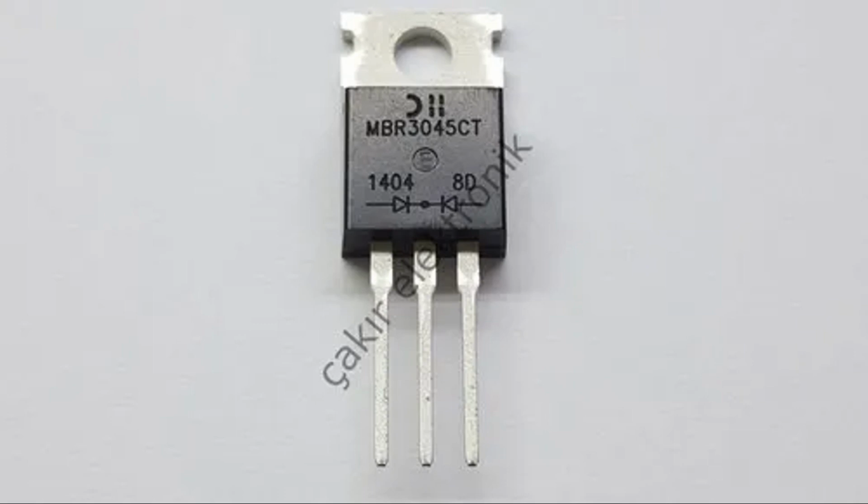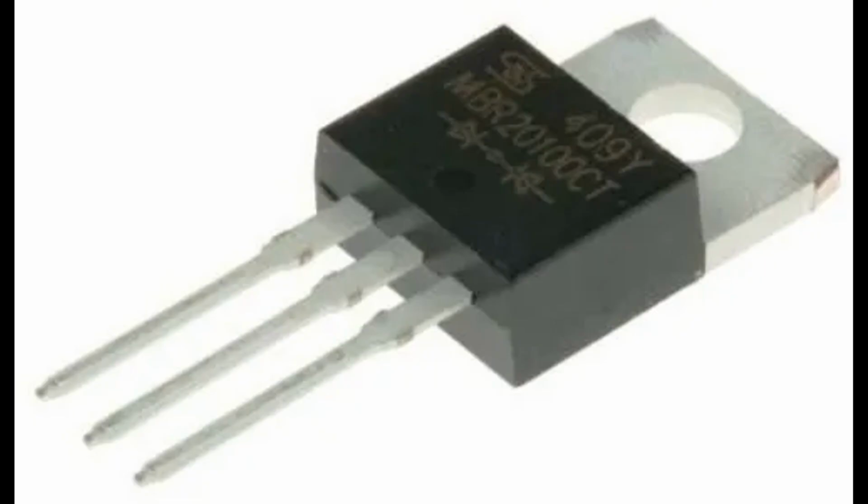Low junction capacitance is a characteristic of certain semiconductor devices, particularly diodes and transistors, where the capacitance at the p-n junction or the gate channel region is minimized. Capacitance is the ability of a device or structure to store electric charge, and junction capacitance arises at the interface between the p-type and n-type regions in a p-n junction diode or the gate channel region in a field effect transistor, FET.